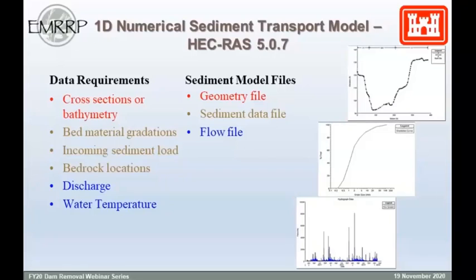For the sediment data file in the HEC-RAS model, you need bed material gradation. You need to define your gradations at every cross-section along your reach. You also need some information about the incoming sediment load, what's coming into your system. That's typically used to define your upstream boundary sediment condition in the model. It's ideal if there's any bedrock location that you know of through data collection or geologic maps.